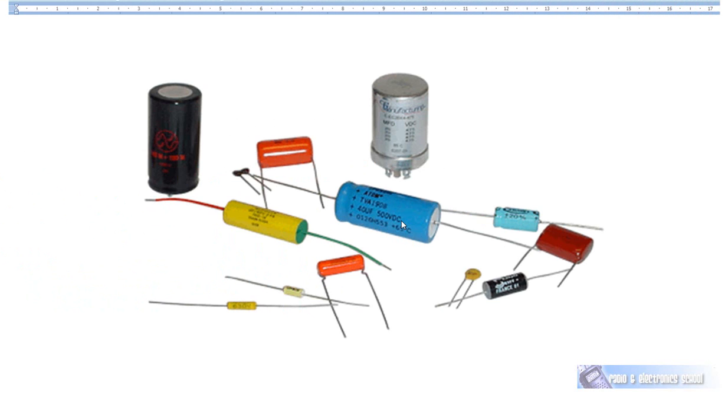And here we have some examples of capacitors. Now remember, they're rolled up. You saw the diagram earlier. The dielectric and the two plates are flexible, and they're rolled up into a cylinder and packaged as they are shown here. This is an electrolytic capacitor. You may be able to work out there that it says 40 microfarads, 500 volts DC. Capacitors are given two ratings. They're given their capacitance, in this case 40 microfarad, at least it looks like 40 microfarad to me, and this capacitor can withstand 500 volts DC.